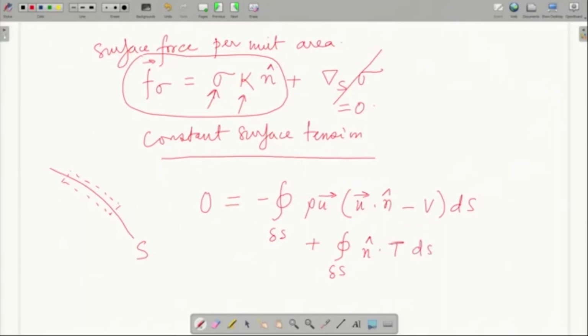so, you remember that this is the stress tensor. So, the integration is around the edges of the control volume. The control volume happens to be this, say the delta V. As far as these two terms are concerned, the first two terms are done that way, and therefore, we have represented it as elemental surface area ds, which is comprised of the periphery, whereas the volume is what is enclosed.